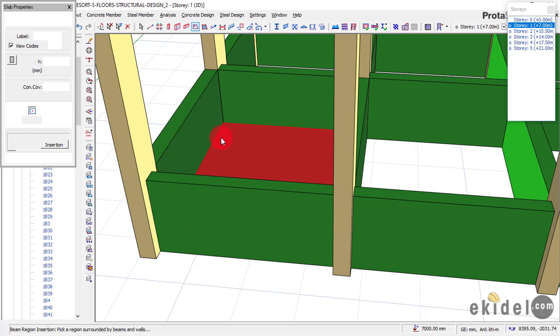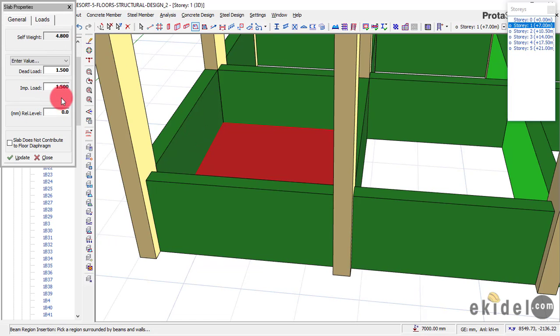And how do you get your relative level? Relative level is gotten by this level you're seeing here. You get the level by using the depth of the beam, which in this case is 1.7, and subtracting 200, which is the depth of the slab, and the cover from the depth of the beam. That gives you relative level.